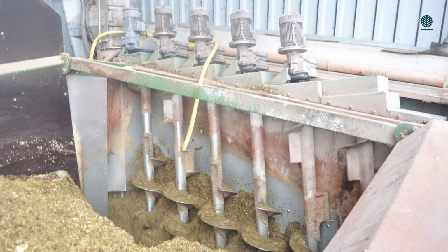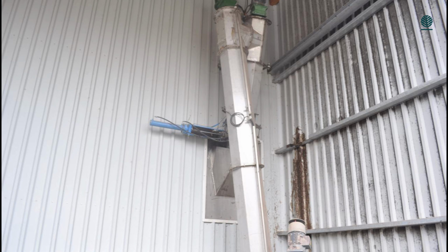So we take out the biogas, we take out the carbon, so the dry matter content lowers. And at the end of the digester, we are around 15, 16% dry matter content. This you can only get if you feed dry. If you feed it wet, the pump is limited to 12, maybe 14% in the inlet. So in the incoming substrate to the digester, the bacteria do their work, and outcoming you're only between 6, maybe 8%. So you will never get more than 8 or 10% dry matter content if you feed wet.